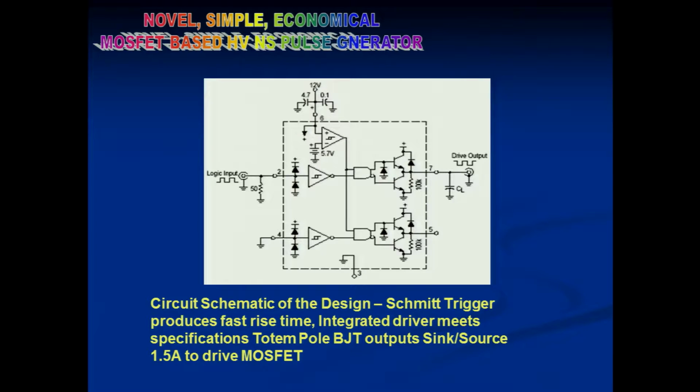I think knowing every individual component is difficult, so all you have to know is that you need a signal source, a nanosecond pulse source, a driver or controlling or pulse forming stage, and then an output stage. Typically it is really simple; if you want to know the concept, everyone knows the exponential pulse, everyone knows a capacitor. So, you charge a capacitor, what will happen?